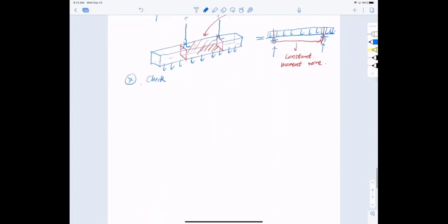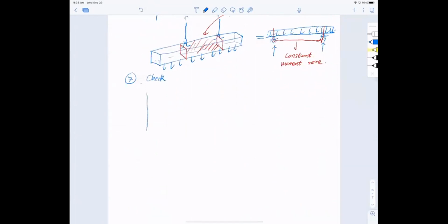Let me ask you the other way. I have bars, right? How many bars do I have? We have 2 number 9 bars. Right, 2 number 9 bars. So what is my beam width? What is b? 12 inches. So if I ask you to put 2 bars in the beam, do you think you can do that? As long as I know how high they go. And you said 2.5 inches last time, the concrete cover.